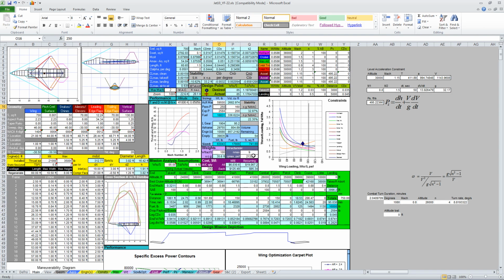Okay. And it also said that higher aspect ratios would be better. It said 3. The 3 makes the wing really heavy, so I'm not sure I want to try to do that. Let's try 2.4 and see if that is a better situation for us. 2.4 isn't really that good either. How about 2.3? Getting closer, but 2.2 is better than 2.23 where we were. Let's try 2.1.